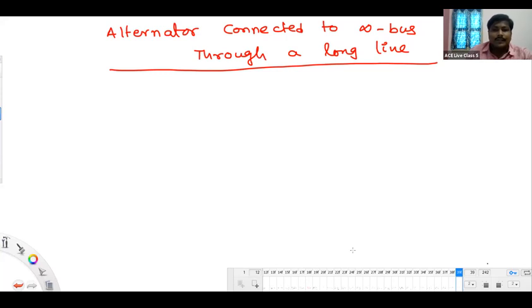Yeah, see, simple, Sai Charan. If the moment of inertia of the rotor body is more, it won't accept speed changes suddenly. It won't decrease the speed suddenly, as well as it won't increase the speed suddenly. That property keeps the speed close to synchronous speed only. In that way, the change in the angle because of an expected disturbance will be less. Okay? Yeah. Next one. Look here.